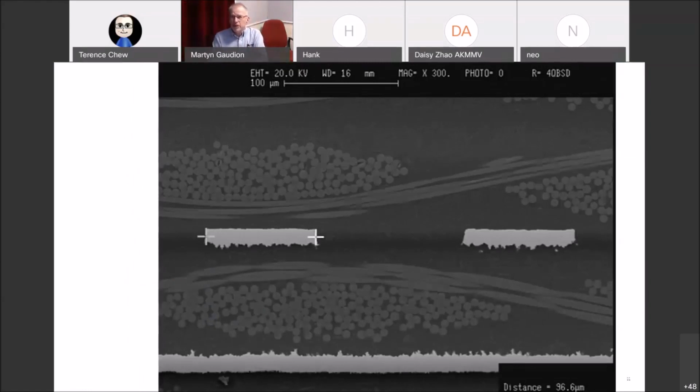Here's a very magnified microsection just to show the roughness. And of course, you can get different degrees of roughness with copper, but also the roughness will change with the treatment of the material. But this is just to show you where I've shown the pictures of where the current's flowing. It's flowing on the outside edge of the trace, and when you look at the base of those two signal traces, that's where all the roughness is. So that needs to be considered in the modeling when you're modeling roughness and losses due to roughness.